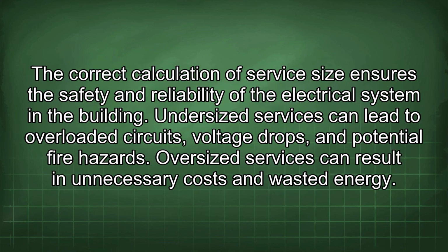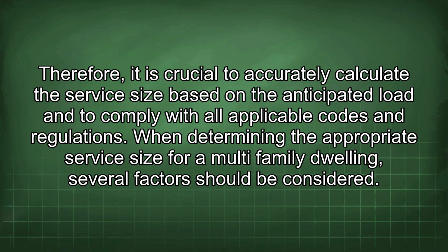The correct calculation of service size ensures the safety and reliability of the electrical system in the building. Undersized services can lead to overloaded circuits, voltage drops, and potential fire hazards. Oversized services can result in unnecessary costs and wasted energy. Therefore, it is crucial to accurately calculate the service size based on the anticipated load and to comply with all applicable codes and regulations.